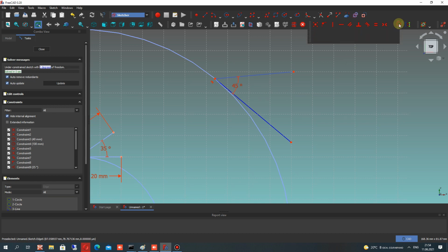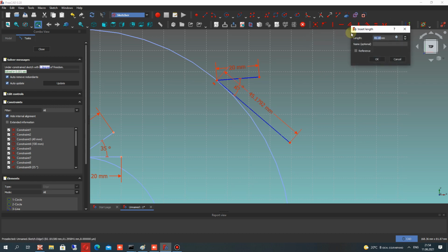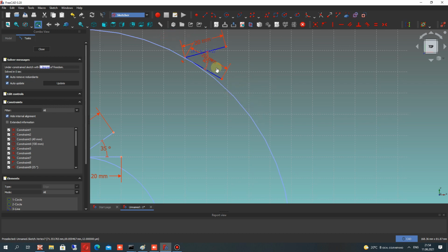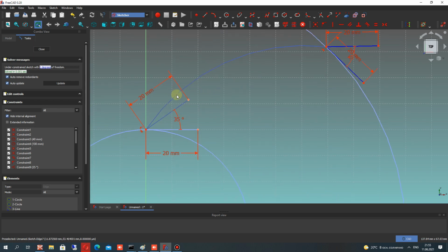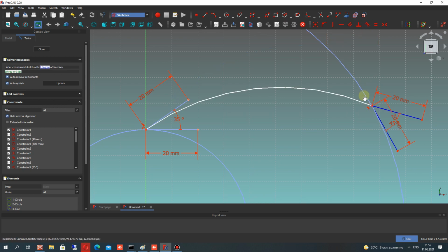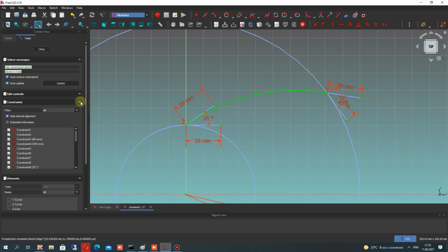Now we can see that we can change the position of the line. Let's set lengths for these construction lines, and let's try to change the point position. So now we have to connect this internal with the external diameter. Let's change the working mode in the Sketcher menu bar to real lines, and let's choose this circle part. Let's set some random position for our blade shape, and let's choose the circle part and line and set the tangent condition. Let's repeat the tangent condition for this.